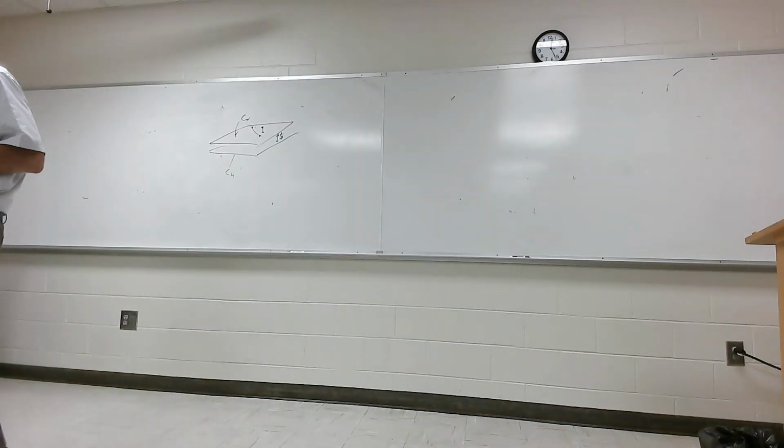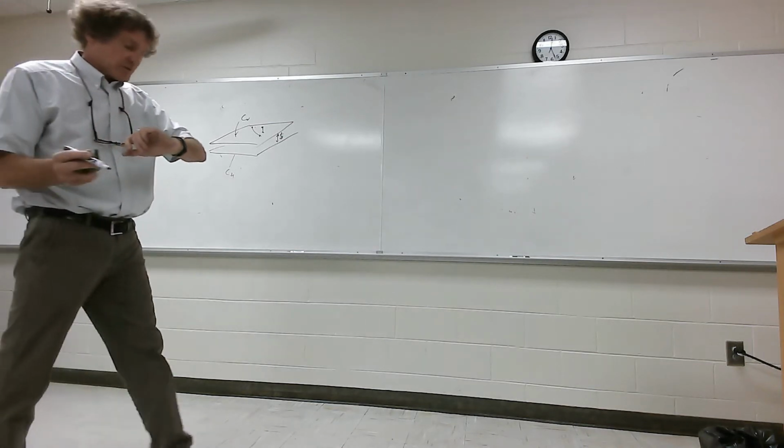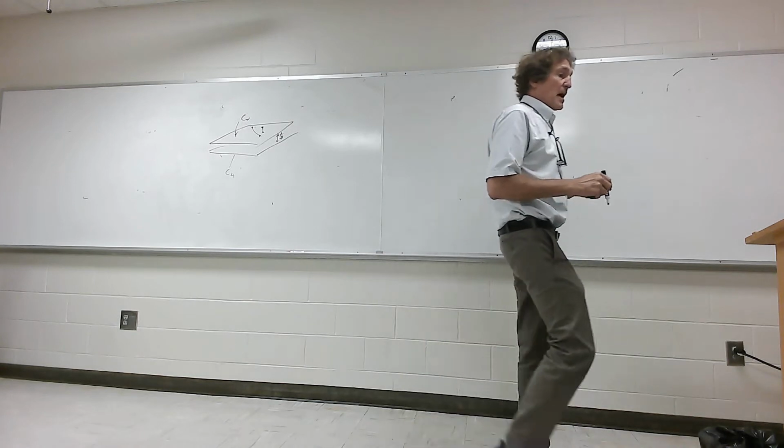It's not hard to use, but you have to be clear that the thickness of that board and the line width that you get will determine the characteristic impedance of the lines. It's real important to match the impedances. If you're 50 ohm input impedance, you want 50 ohm lines. So he has a bunch of stuff about impedances in there. I'm going to stop there.